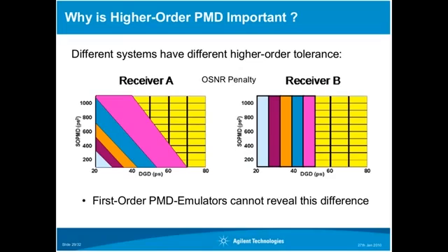And interestingly, the 100 gigabit receivers have a lot of influence on this kind of behavior because most of the receiver properties are coming from some sort of FPGA or ASIC software. So now moving to 100 gigabit, you really have a handle on optimizing your receiver with respect to PMD tolerance. I think this is a thrilling point, that you really can use these test and measurement approaches to optimize your receiver with respect to all these parameters.